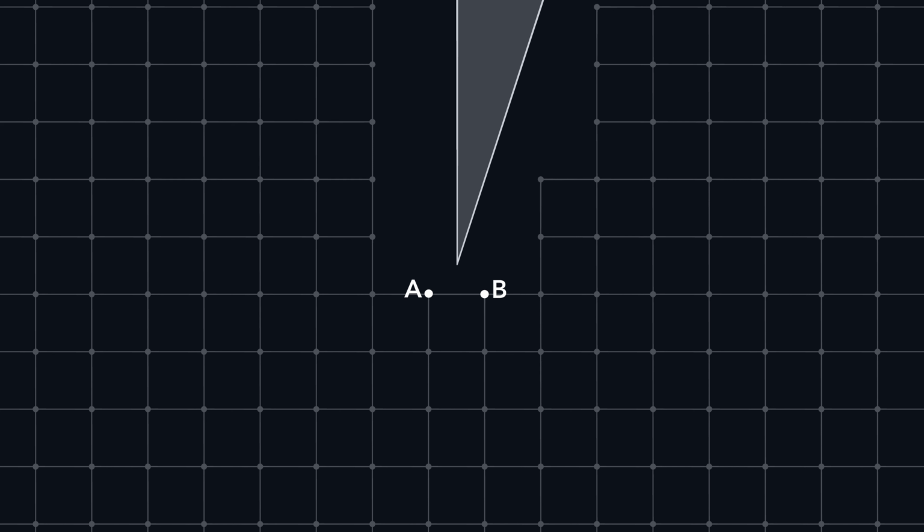Returning to our original problem, we simply calculate the distance from the edge the robot is traveling on to all the edges that make up the room or any obstacles. If any of these distances is less than the robot's radius, like in this example, we remove the edge. Of course, we'll have to do this for all the edges. This finally gives us a map that will work.